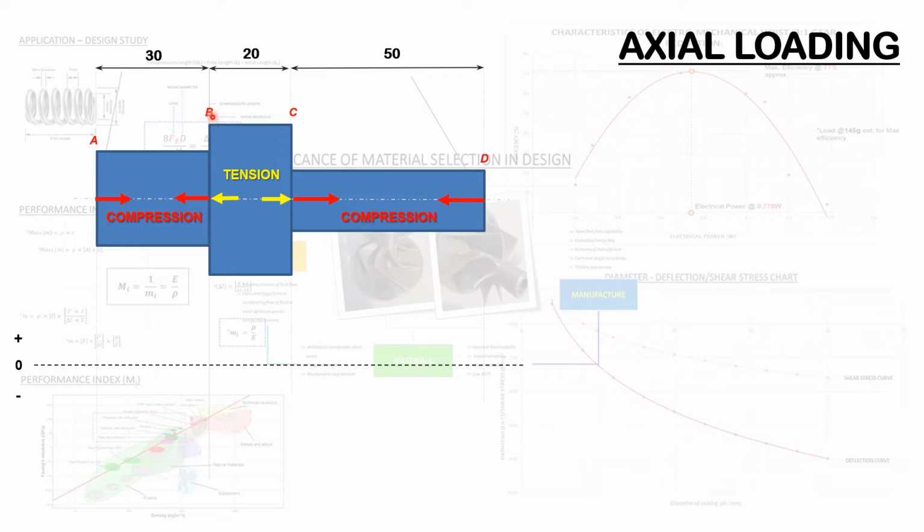When we come to BC, this is where we have two forces that are causing compression on section BC. Thus, internally, BC needs to generate an internal force to counteract the loading acting on its surface. So the internal load in this case will be in tension to cause section BC to be in equilibrium with respect to the external stimulus causing deformation to it.